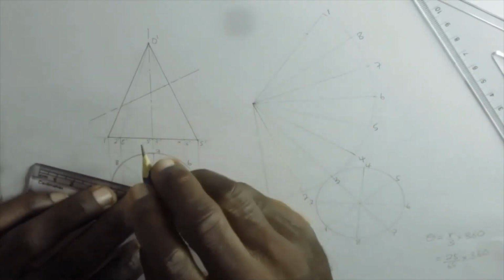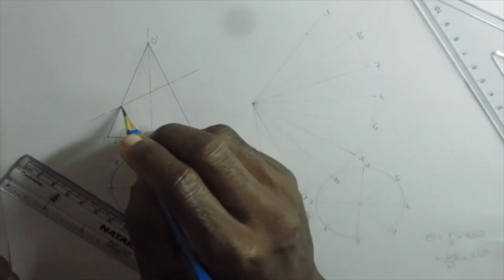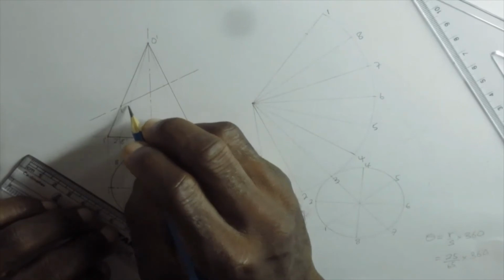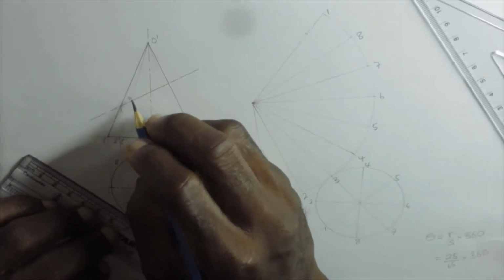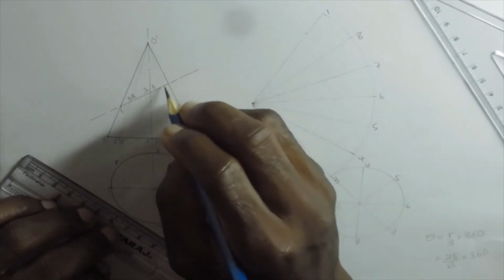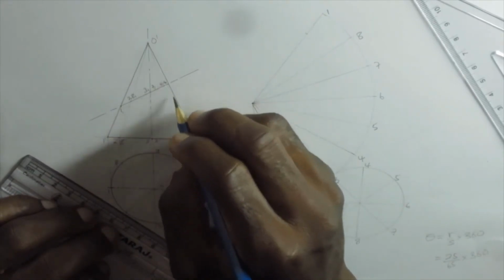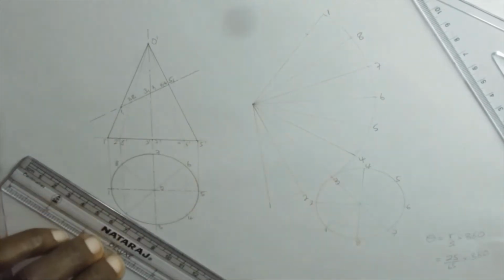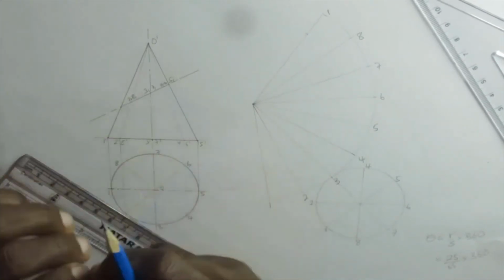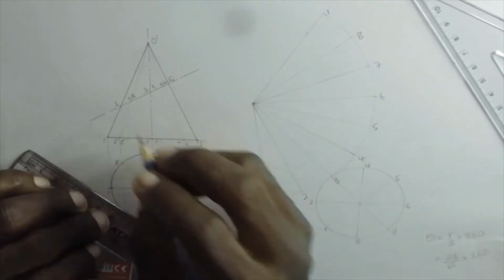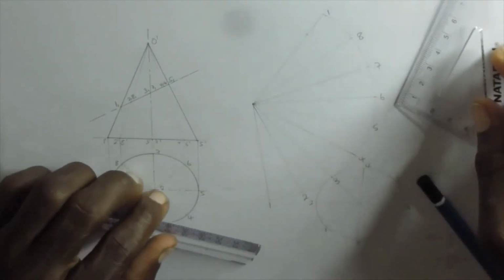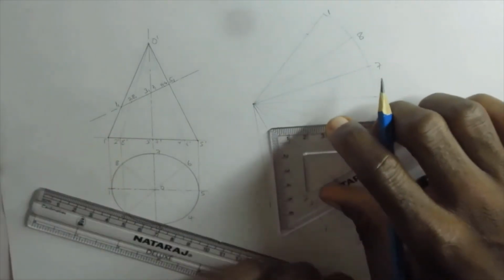Now that we have drawn it, we need to indicate, because we are removing the top part and the base is what we are dealing with, so that when we are developing it, it will be easier for us. So we have to label each of the points where the cutting plane is cutting the generators, those lines we have drawn to the apex of the triangle. Okay, so we label it. The one along 1, we have 1 subscript 1. Then the one along 3 and 2 and 8, we have 2 subscript 1, 8 subscript 1, up to the last one, 5 subscript 1.